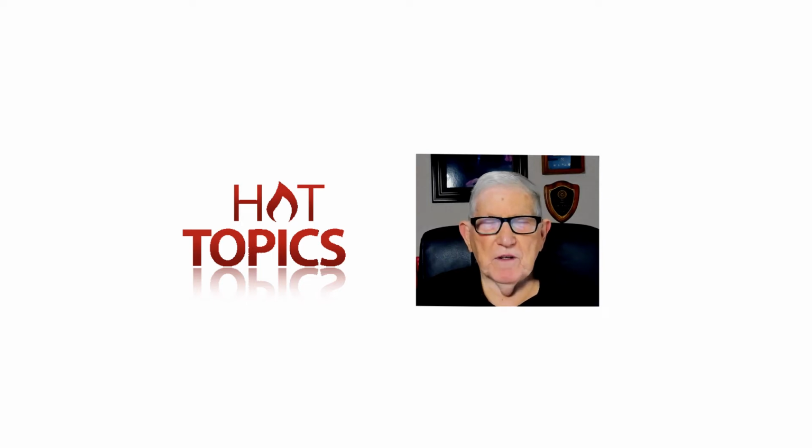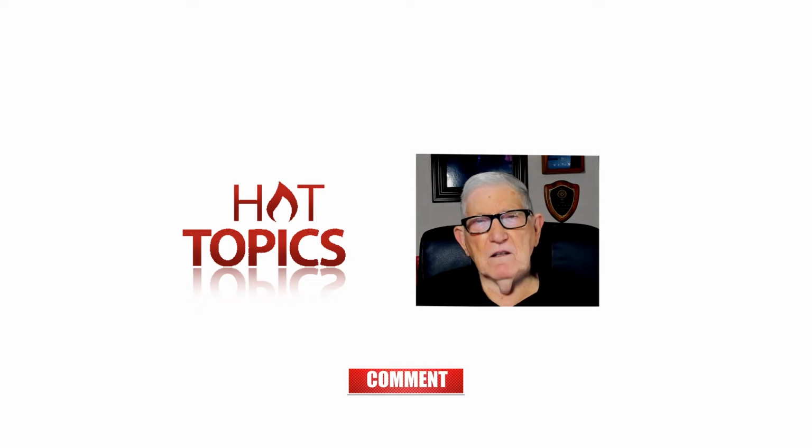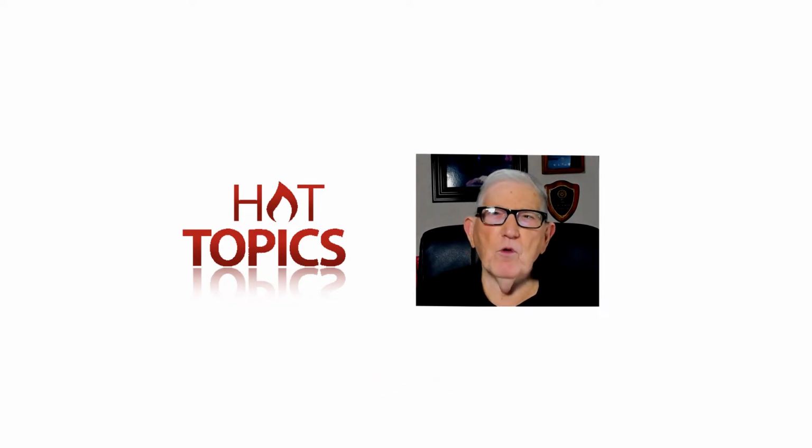Welcome to Hot Topics. In this video, we're going to be discussing what's the difference between the working clearances in Table 110.26(A)(1) and the approach boundaries of 130.4 that we will look at. I think it's 130.4 F through G, around page 25 of 70E.